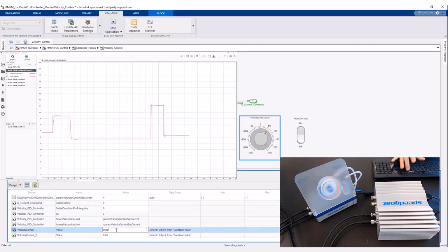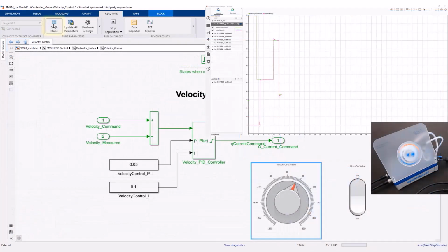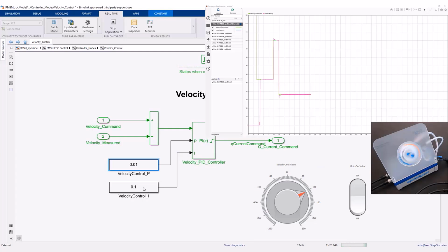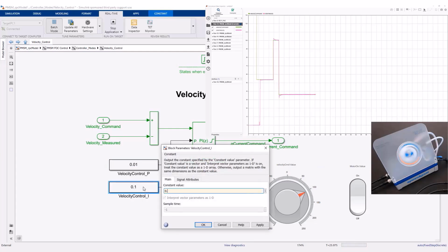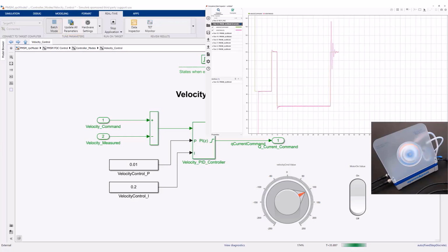Depending on your application, you might need to update multiple parameters simultaneously to test a desired effect. We activate batch mode on the real-time tab, and then we can adjust all the parameters we need. The changes will only be uploaded to the target machine once we click Update all parameters. To switch back to normal mode, simply click Batch mode again to deactivate it.